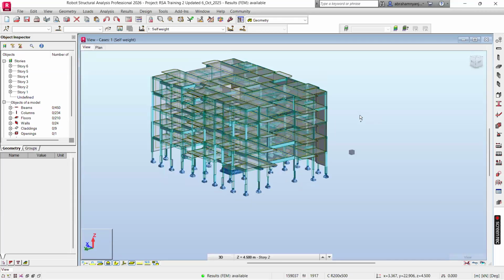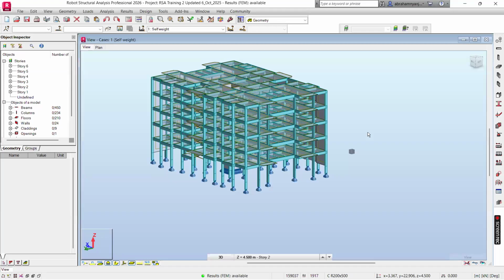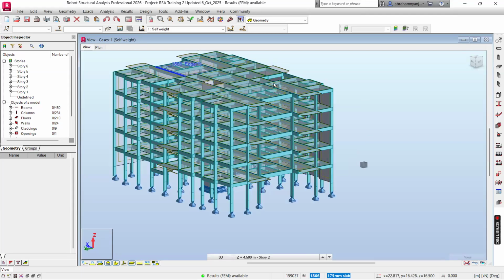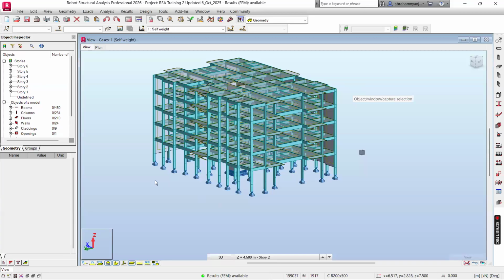As I highlighted earlier, maybe for those that have just joined us, foundations are critical. You might have a structure that is perfect, all elements are functioning properly, but if you didn't carry out very good geotechnical investigations, you might end up encountering soils that will undergo swelling, or that will create differential settlement.